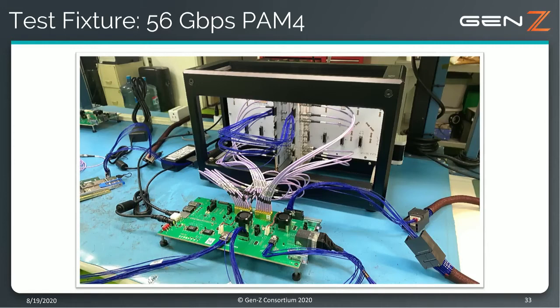And what we're doing with that board, you can see we donate some of those signals to other connectors that we manufacture. You'll see two rather nice brass-looking connectors there. The one on the right is our Bullseye 40 connector. And what we're doing is we're taking 4 channels of PRBS 31 data, 56 gig PAM4, and we're taking those 4 channels to one of the riser cards through about 14 inches of coax into some SMA connectors.